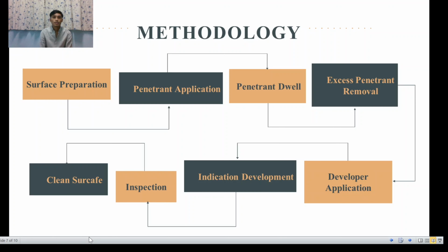Liquid penetrant testing is a non-destructive metal inspection procedure used to check for failures. It is a common method used to inspect welds. There are eight process steps to do liquid penetrant testing. The first is surface cleaning preparation. The surface must be free of oil, grease, water, or other contaminants. The sample may also require etching if mechanical operations such as machining, sanding, or grit blasting were used.